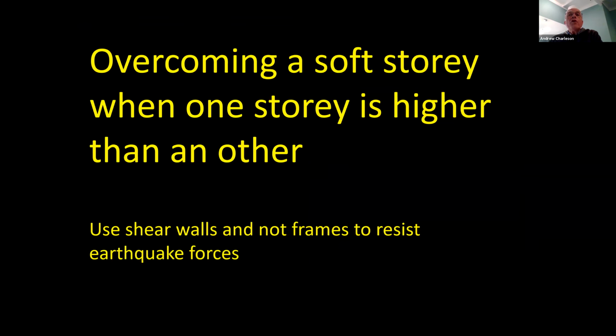Now, if you have a soft story when one story is higher than another, then you must use shear walls to resist the earthquake force. And I'm sorry, you cannot use moment frames because the moment frames will form a soft story. But if you use shear walls, they do not suffer from a soft story situation.